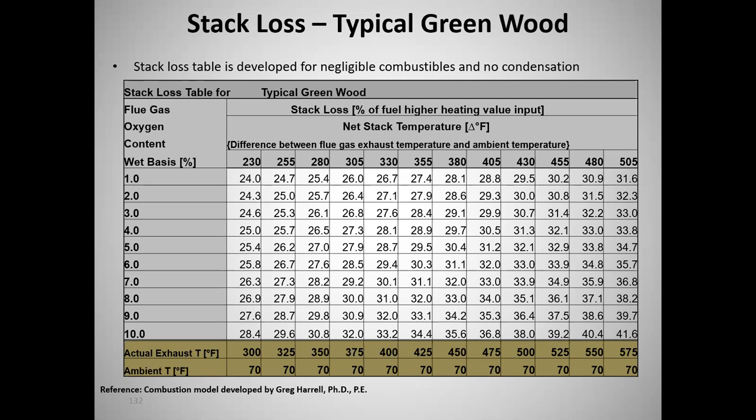But they'll heat it up to like 180 and cook it for a while, and then they slowly cool it off. And they'll dry that moisture content down to between like 6 and 8%, which is the wood that they would sell to a furniture manufacturer, or somebody making pallets, or somebody constructing something out of wood. Those people don't want green wood. So there's a whole industry.